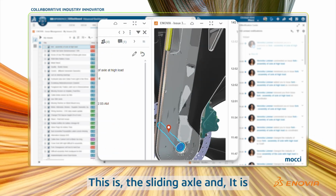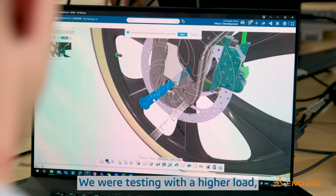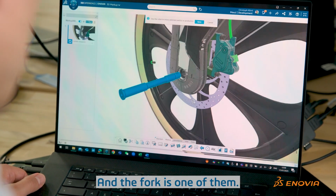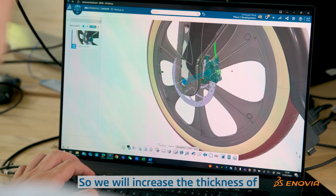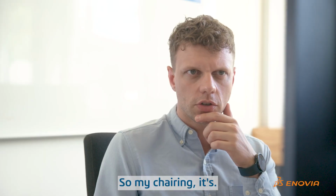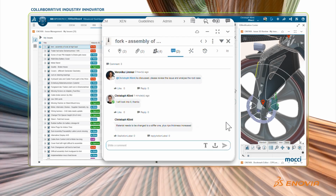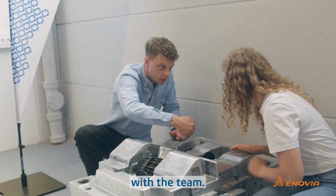This is the sliding axle, and we were testing with a higher load, and we expected some parts would have to be changed, and the fork is one of them. So we will increase the thickness of the fork and change the material, and that should resolve the issue. So I added a comment that we need to do this, and the next step will be to discuss this with the team.